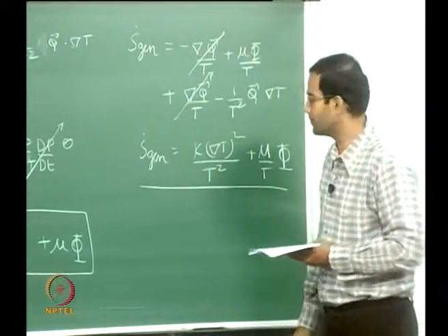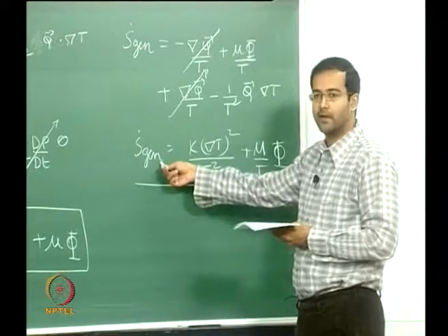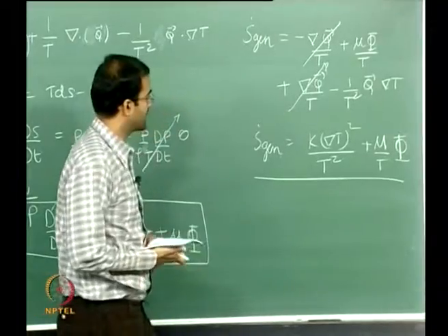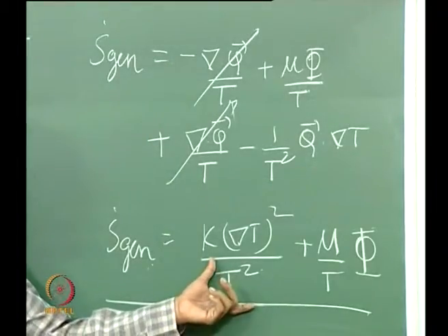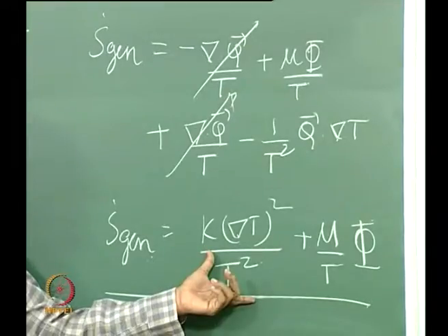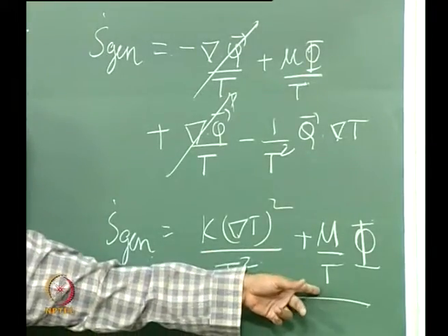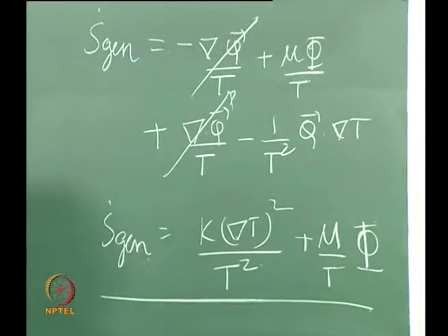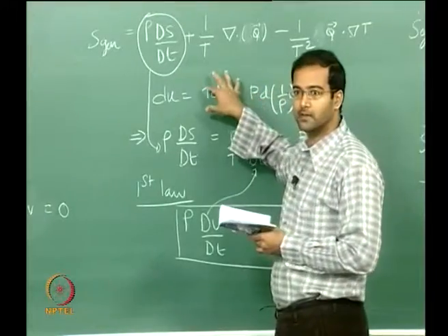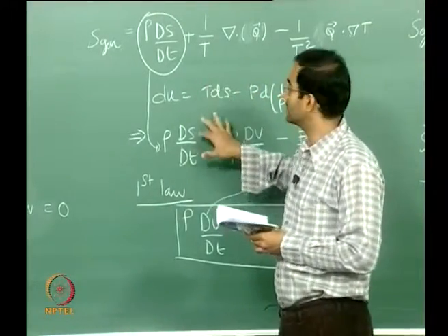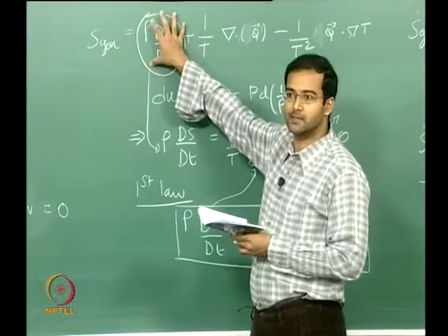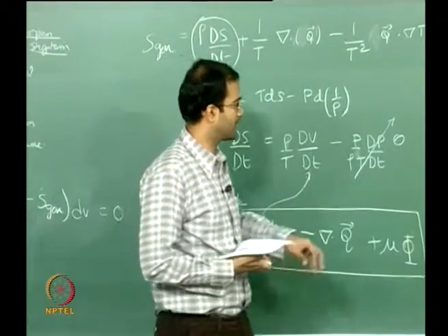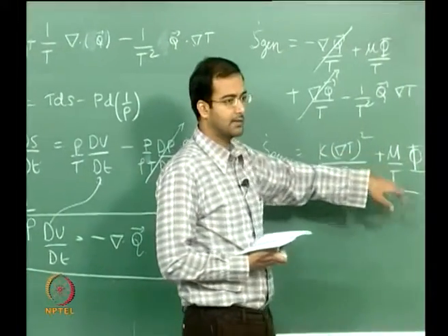okay. So therefore the components of entropy generation are two. So one is coming from the entropy generation due to the conduction part, okay. So within the system the conduction of heat, the other is due to the viscous dissipation, okay. So this part till here I think it's straightforward, only after this we apply the Gibbs law and just manipulate a little bit so that we can eliminate some of these total derivative terms, okay. So finally we write everything in terms of the heat transfer by conduction and the viscous dissipation.